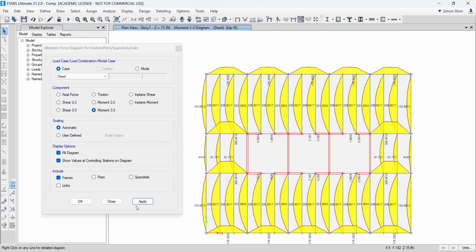When you turn on the moment diagram for the dead load uniform load, you see the moment diagram. We exercised this last week, right? W L squared divided by 8, uniform load on the beam. Uniform loading times tributary width makes a line loading. If you have a line loading, W times L squared divided by 8 gives the maximum bending moment, because we are using uniform load instead of point loading.